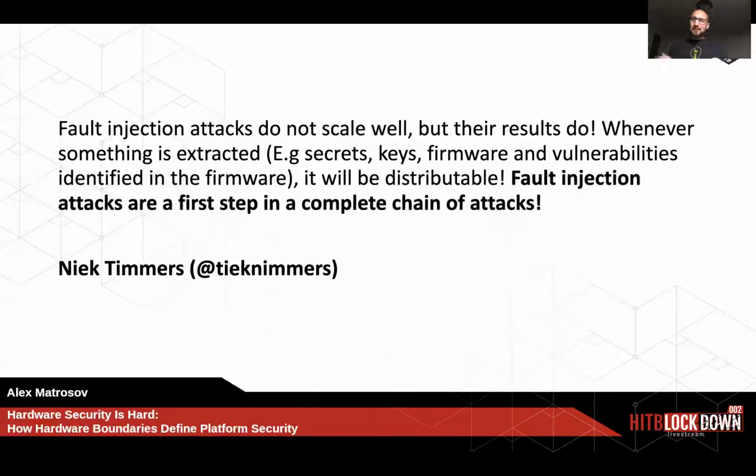Another thing I want to draw your attention to is fault injection attacks, because a lot of small chips don't have good protection from fault injection attacks, like voltage glitching, electromagnetic fault injection, and many others, or from power side-channel analysis.